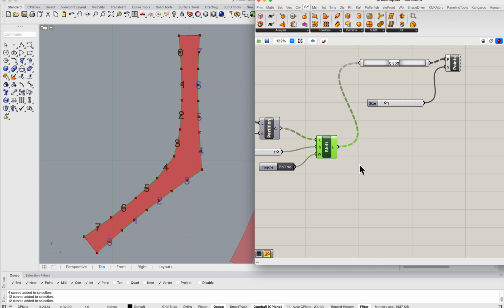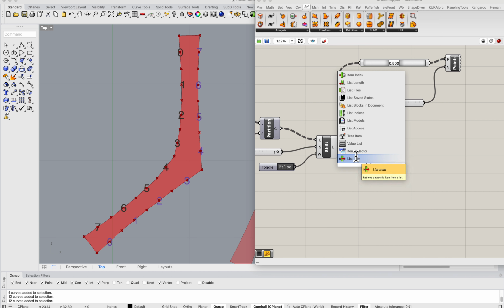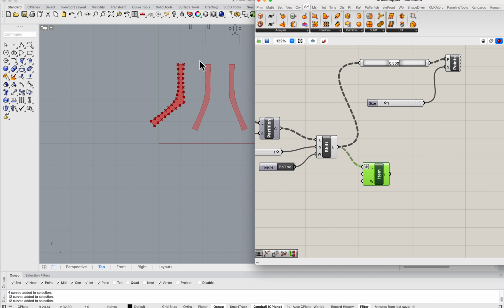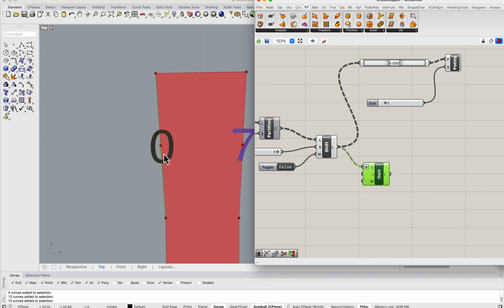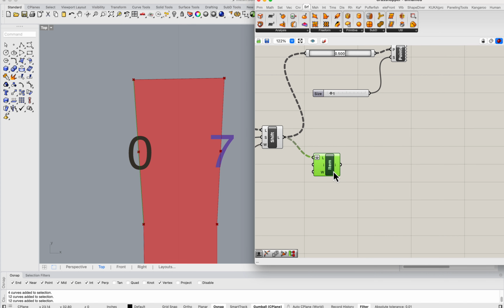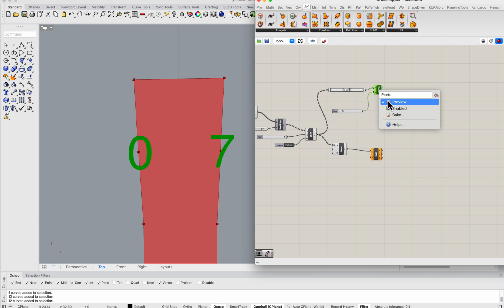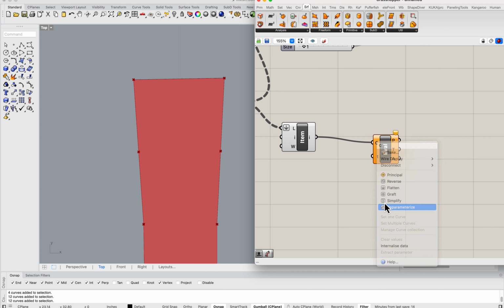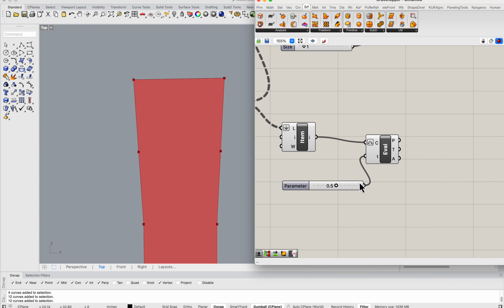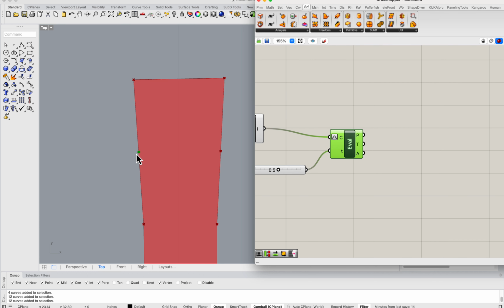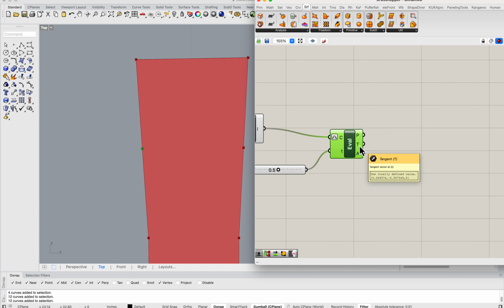Okay, once we have these edges, let's look at one of those and how we process the flange for this hole for the zip tie basically. So I'm going to first start by evaluating the curve. So if you do evaluate curve, let me hide the points. I'm going to reparameterize the edge and then do a midpoint evaluation. This gives me the tangent vector, and we need a plane construction here so that we can place the rectangle for the zip tie.